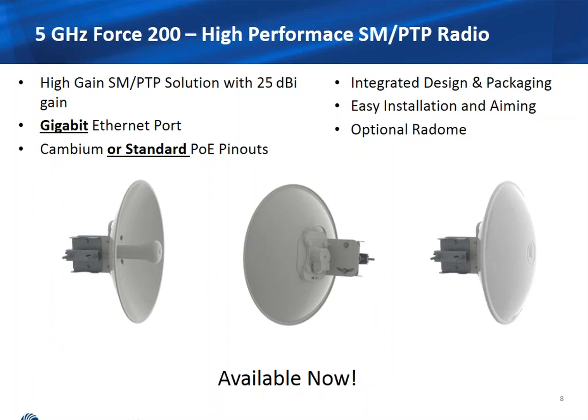John, we did have one question. You talk about the PoE being standard. Is that also at the gigabit port? Can we do a gigabit with a standard PoE? Yes, you can. Let me just emphasize that it's standard pinouts. It's not the 802.3 AF or AT standard voltages. But it's a low voltage 25 to 30 volt powering scheme.